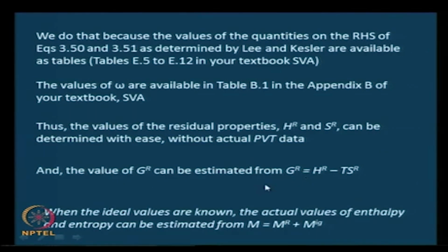And once the ideal values are known, we have already seen how to get the ideal values in terms of PVT and so on. The actual values of enthalpy and entropy can be estimated from the definition of the residual property. Residual property was actual minus the ideal, and therefore the actual is residual plus the ideal gas property.